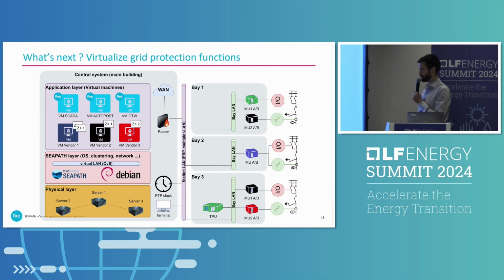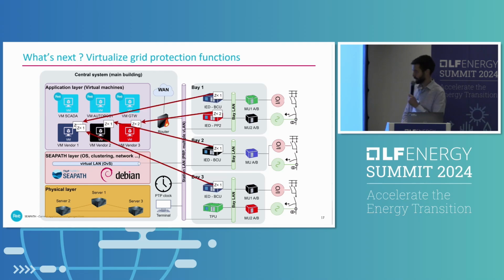So yeah, I wanted to say something about this. We talk a lot about virtual IEDs. We don't want to use the term virtual IEDs, because when you talk about virtual IEDs, normally you think that this is one IED, but we want to group several IEDs in one virtual machine. So if we talk about virtual IEDs, we may think that one virtual machine equals one virtual IED. And that's not what we want, because we want to limit the number of virtual machines on the system.